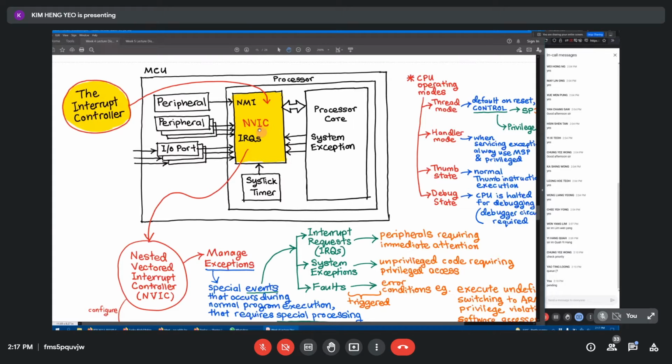So you have no choice, you have to write code there to check who caused the interrupt, right? Because the PIC microcontroller has many interrupt sources. You don't know. But the vector V here means the processor will automatically run the correct interrupt service routine, the correct ISR for the interrupt. You don't need to check, right? Here is how it happens.